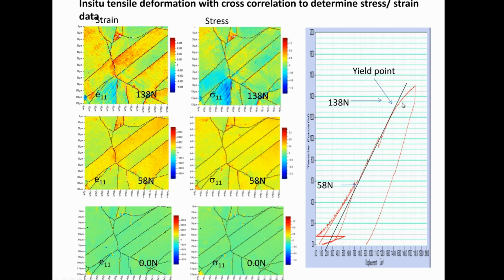We have a tensometer, the work being done by TSL Laboratories in Japan, who build the tensometers. And here we are increasing the load on the sample. The axis of loading is horizontal in this case. And in this region, up to here where it's a straight line, this is the elastic region of the material, and here it starts to become plastic, whereas it goes over there. This is where dislocations are thought to start to be generated to enable the plasticity.